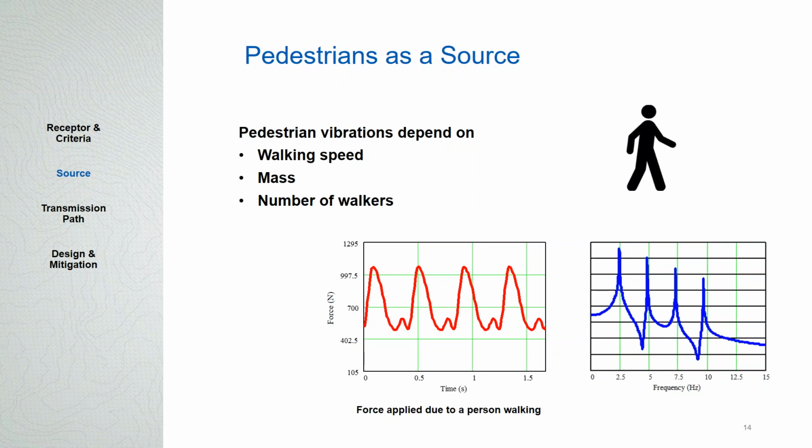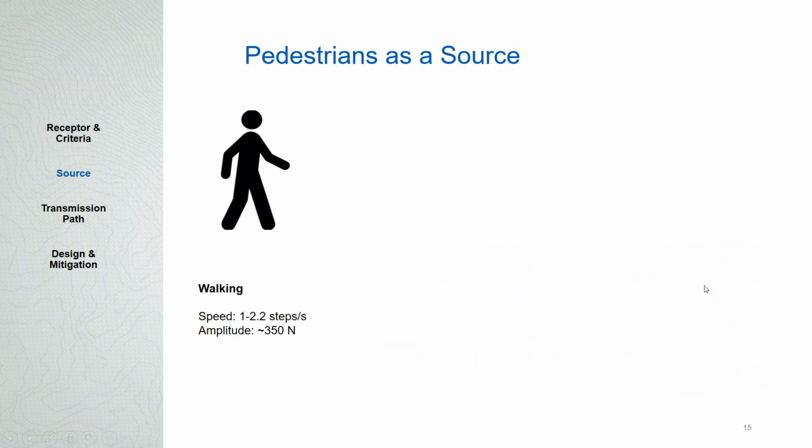But you're probably thinking, well, often floors are a lot stiffer than that, and they are. They're maybe in the range of around 10 hertz or so. There's a lot of floors, 6 to maybe 15 hertz. So you might say I'm clear, but no. In fact, at integer multiples of your walking frequency, you actually get another kind of resonant force that could be applied. So we're seeing another at 5, 7.5, and at about 10 hertz. So if you have a floor with a frequency of 10 hertz, which is not uncommon, that walker is exciting that floor just because they're walking at a speed that's, in this case, 1/4 of the resonant frequency. So that's great.